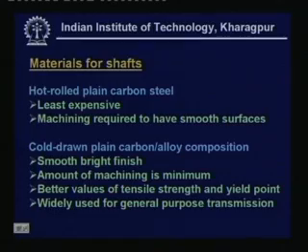It is a very utilized material because of its cheapness, but because it is hot rolled, there is always some amount of scaling present, and some sort of machining is always required to make its surface smooth.